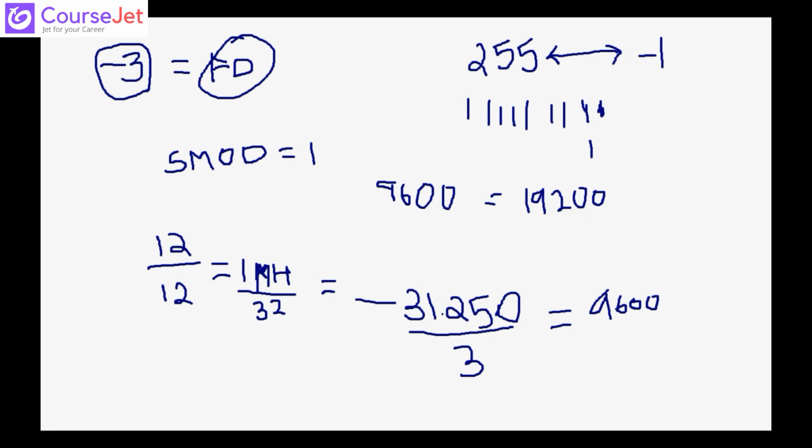Next, we use the SCON register, and as I said, we will enable the receiving option also, so the value becomes 0x50. We are using 01 for serial communication mode 1, and the rest of the bits are zeros. Receiving enable is 1, so here you will have SM0 as 0. This 01 is for mode 1.